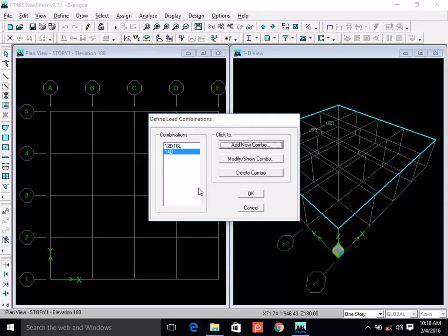No live load. The very first in the list of combinations is 1.4 dead, only 1.4 dead, no live. The second is 1.2 dead plus 1.6 live. You can see these load combinations in your steel book and also in your concrete book. Yeah, in the very first chapter.